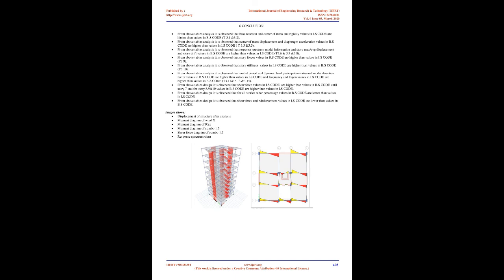In general, a pier is an upright support for a structure or superstructure, but it can also refer to the sections of load-bearing structural walls between openings and different types of column. Piers are most commonly made of concrete, masonry or treated timber, and installed into prepared holes or shafts. They can also be used in foundations as a means of raising a structure from the ground, in particular if the structure is on a slope or near a large body of water.